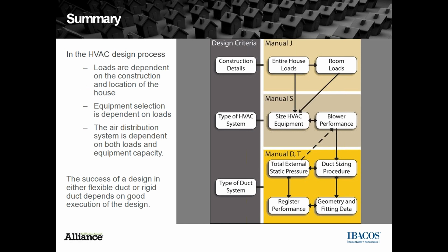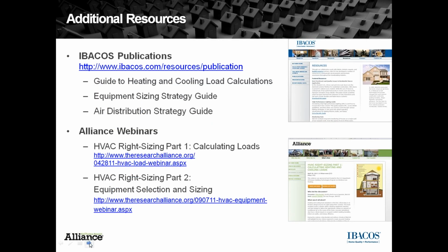We always have to come back to this one because it's just not step by step, do this, you're done. All the back and forth arrows, the dashed arrows back to blower performance. As you design the system, you're going to run into things that are going to force you to go back and redo until you get it right. And in any case, good design must be followed by good installation. Flex duct, stretched, those kinds of things.